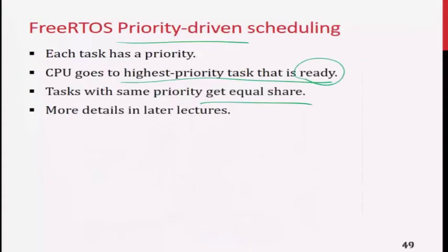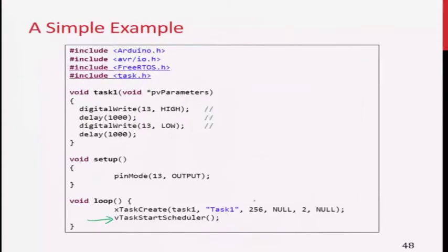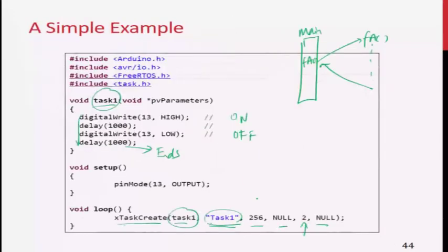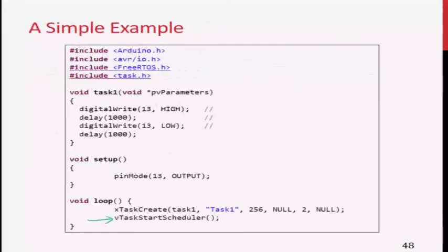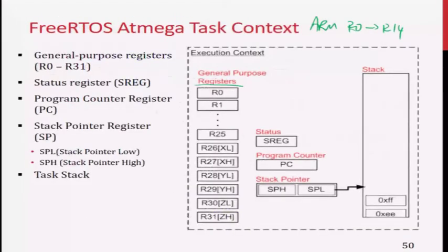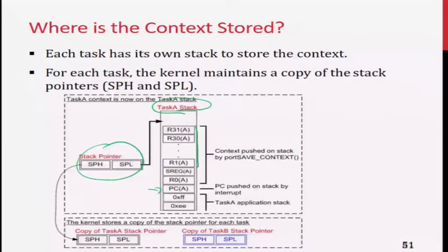So if I look back here, this is your stack. How many bytes? Correct, how many bytes I set aside for my stack. This allows me to save the status of my task before I start doing a context switch.